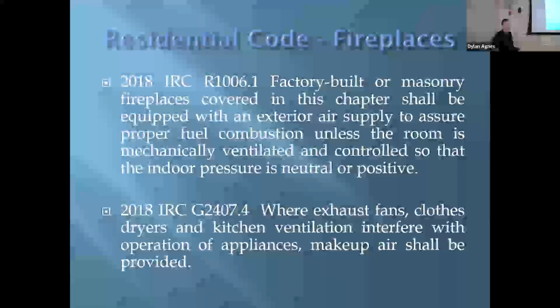So to keep all of my testing consistent, I always use the front door, and I use a standard manometer with a reference hose outside, making sure that it's not in the wind. I have a metal tube that I suspend, usually up higher, 3 or 4 feet off the ground if I have something to hang it on. Then I run the tube under the door and test it against the inside. There's a test you can do to zero it out, or you can just do a common A/B test with a standard manometer. Okay, great. Thank you.